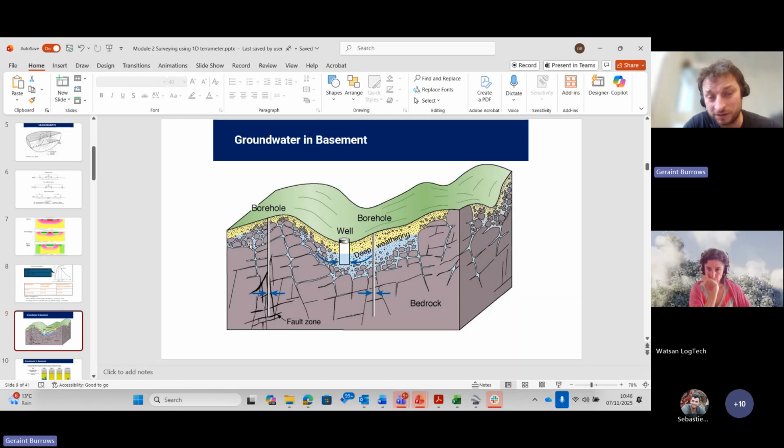In particular geologies, certain structures might not be suitable, like the example about the schists. You might have a deep weathered zone that is clay filled and not suitable for water supply as a target, so you might have to think about something else for a target. You have to understand the geology in order to then decide on what type of signal you're going to get.